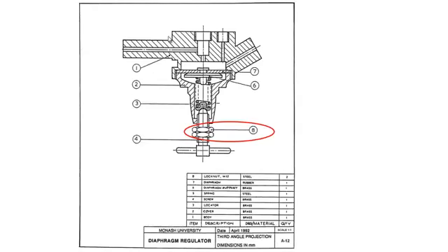You can put it up one way, or you can rotate it 180 degrees and put it on the other way. For these ones, it doesn't matter which way we do it, but if you think about some types of lock nuts, they require to go on one way or another, otherwise they can't actually be fastened on properly, or they won't perform their job correctly.